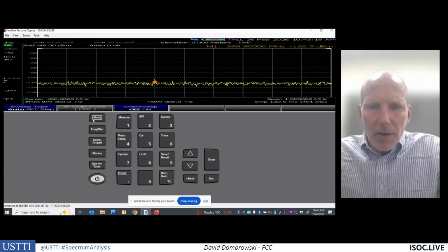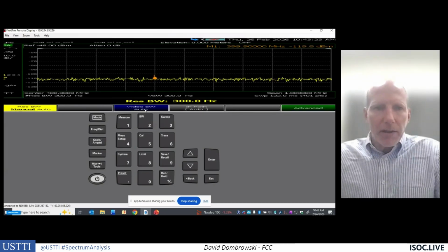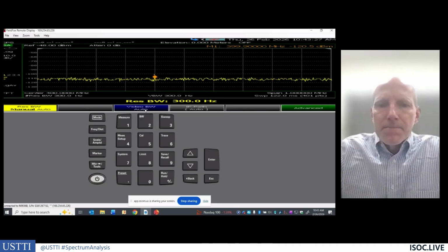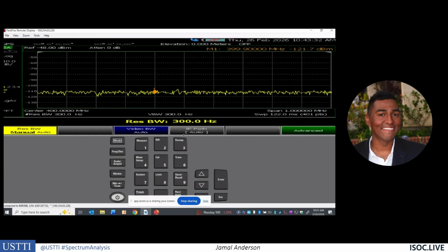And that's how to adjust it on this analyzer. We go to the bandwidth and we just leave it in auto mode and let the analyzer automatically adjust the video bandwidth filter. Okay, next question: for intermodulation products generated by IMT systems that affect the 2.5 gigahertz band,